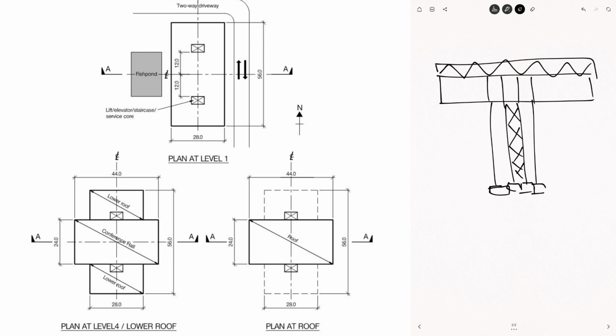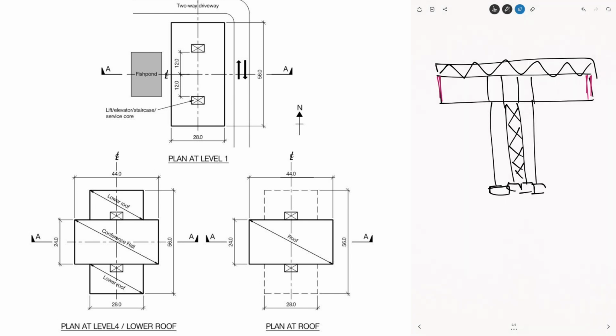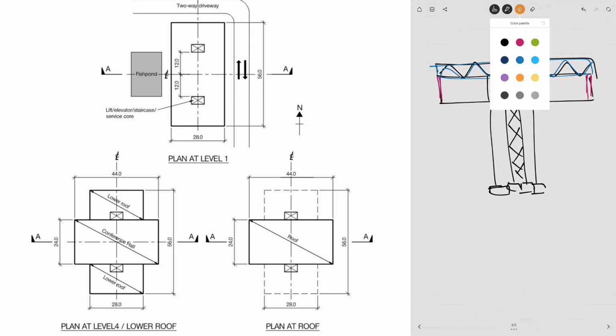You got your steel truss at the top, and you got some hangers here. Steel truss is another of the main elements. Let's put it in blue. The other element we're going to be designing is the bracing, which is normally simple, but it's considered main in this one, and the foundations. So those are the 4 elements that we're going to go through.